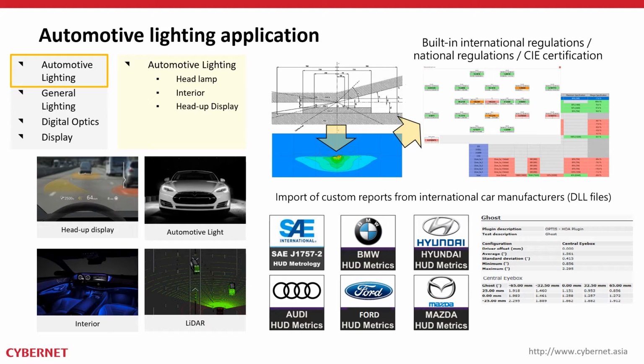Another strength of SPEOS is its built-in CIE international regulations, where SPEOS can help you to validate your design in accordance with the international regulations. Other than that, Ansys also collaborates with major car makers to import their DLL files into SPEOS. Same as above, once the simulation is complete, SPEOS will be able to generate a validation report here, and you can send it to the car maker.